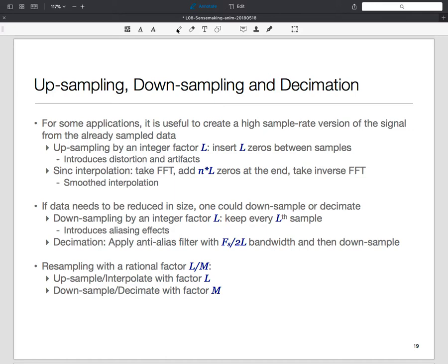Yeah, so it's usually just an interoperability issue. That is, I have to send someone a signal and they only accept some standard data rate signal, right? So maybe my algorithm was trained on accelerometer readings which were at 1 kilohertz, and my sensor is giving me readings at half a kilohertz. So I need to just do that match. So that's the role of upsampling.